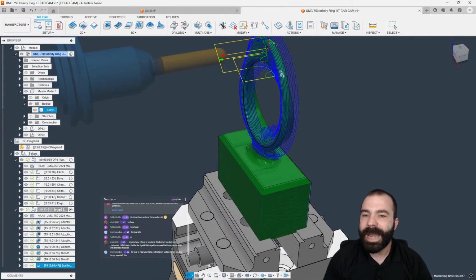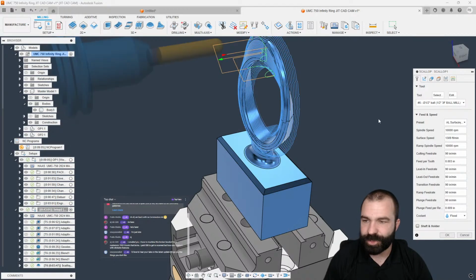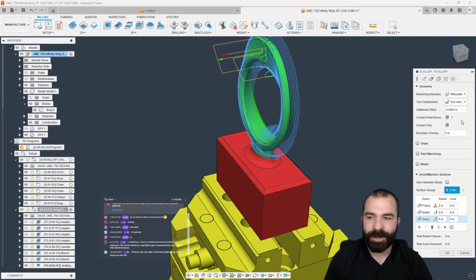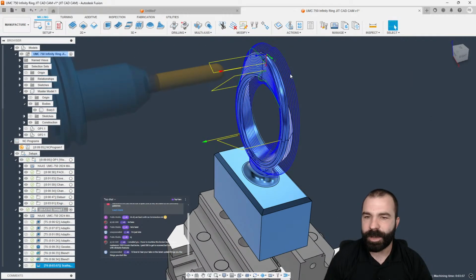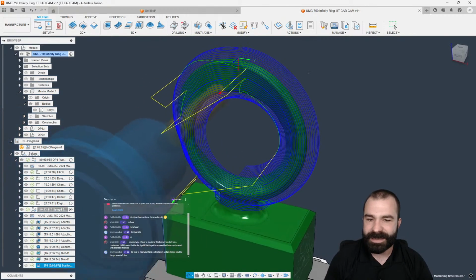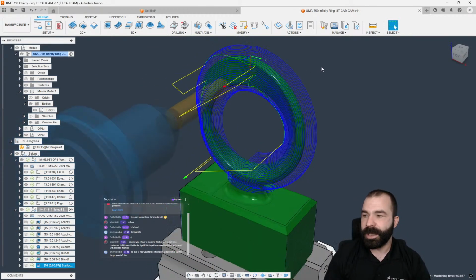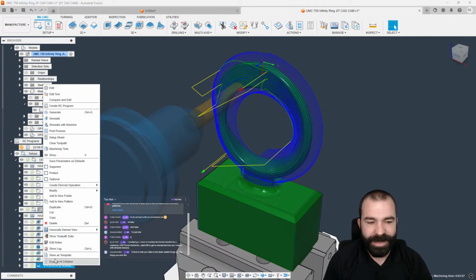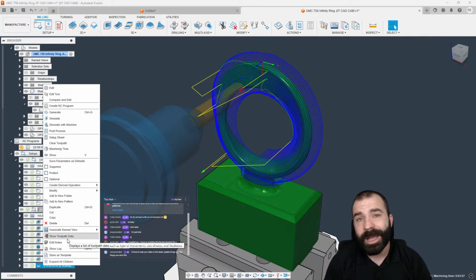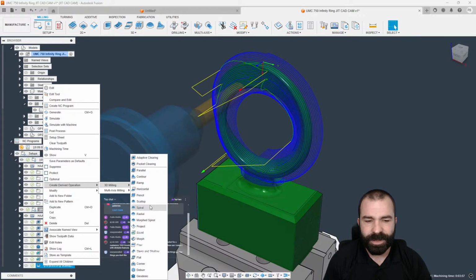You're also now seeing the fact that something like contact point boundary is working for me. Again, reducing my waterfalling. We might be able to actually even remove our additional offset and still not have waterfalling. And then that could lead us down the path of what is going to be the better toolpath for this part. So as you guys are going to see, we're going to go ahead and right click on that scallop toolpath. Now that I've got my blue lines where I want them, I like to now jump around and take a look at a couple of different things.